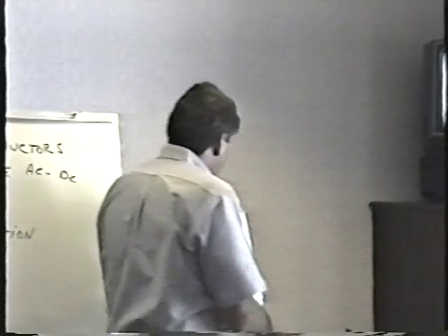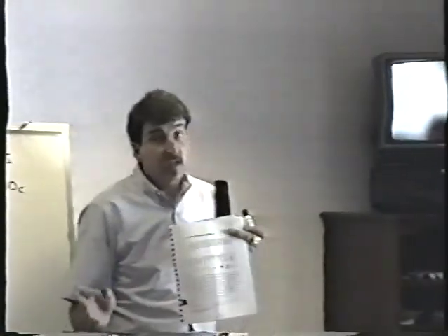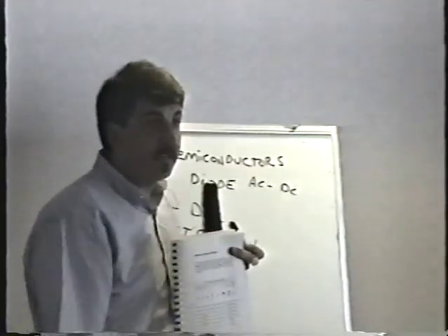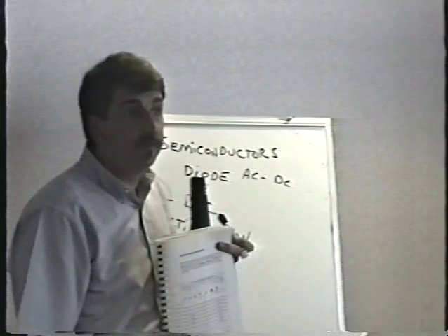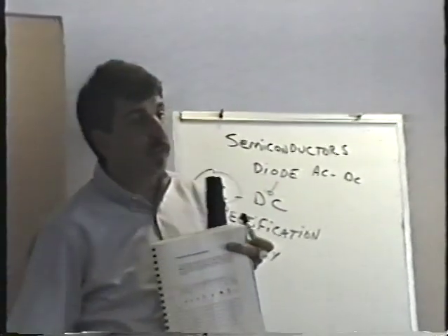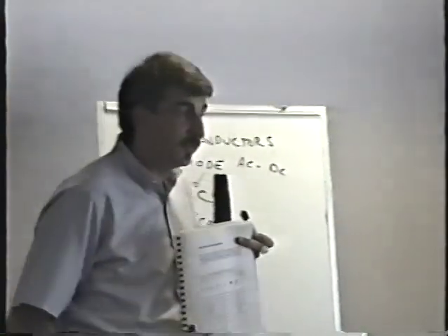And in fact, it's a real common problem on these switching regulator power supplies. Much of the time, and we'll do this on Wednesday, the only thing that's wrong with your power supply is one 25-cent diode. I mean, it's very common. The last class I did, virtually half the problems were just one single diode. You'll see how simple this really is to fix.